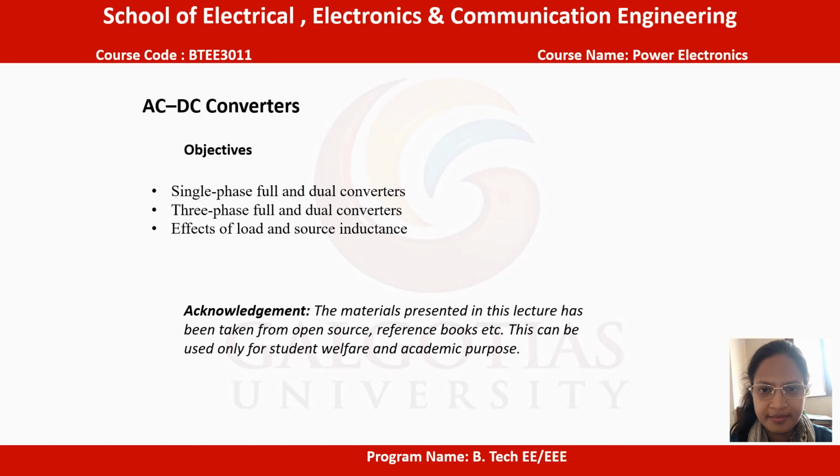In this lecture, we will discuss the controlled rectifiers. The diode rectifiers provide a fixed output voltage only. To obtain controlled output voltages, phase control thyristors are used instead of diodes. The output voltage of thyristor rectifiers is varied by controlling the delay or firing angle of thyristors.